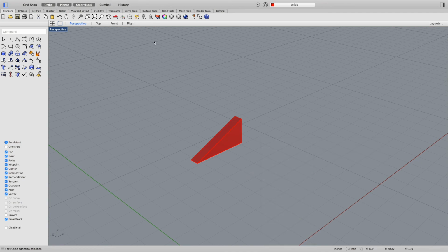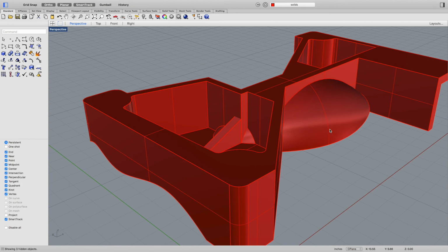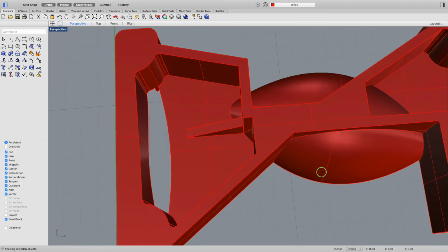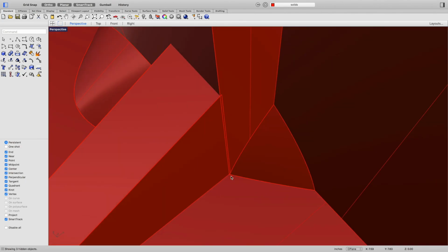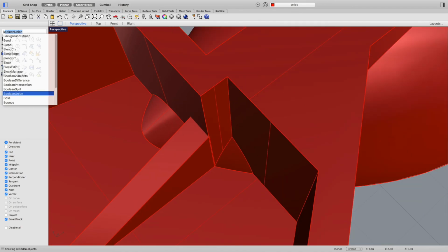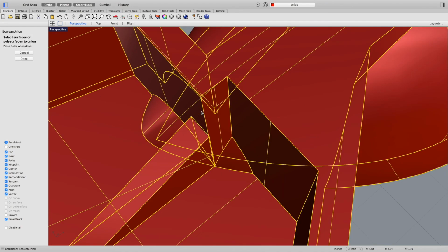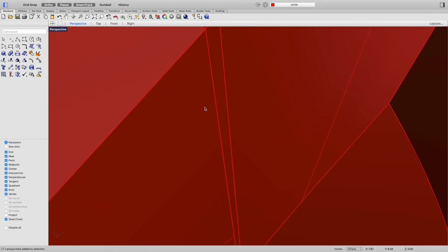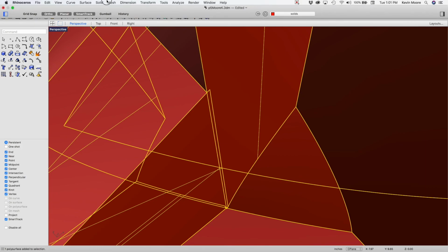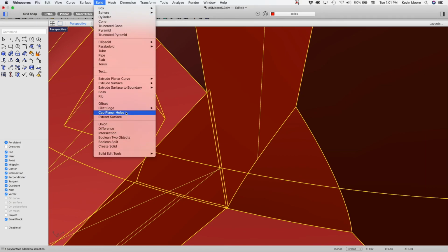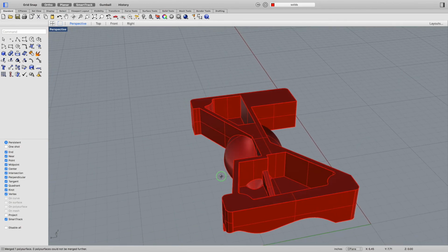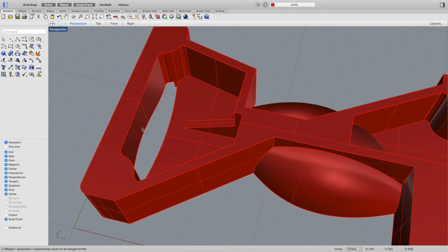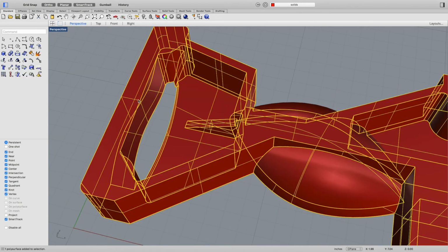And bring back our objects, show object. Okay. And if I Boolean union this to this, should clean it right up. And then go to solid. Solid edit tools, faces, merge all faces. Cleans that right up. Got that point. And then the one other thing we're missing here is that little circular piece there.